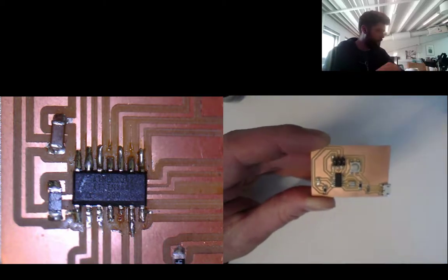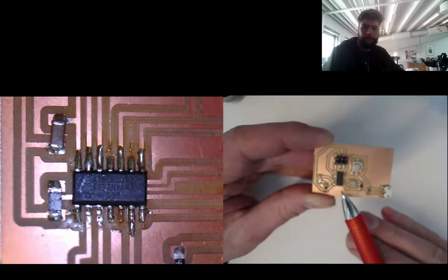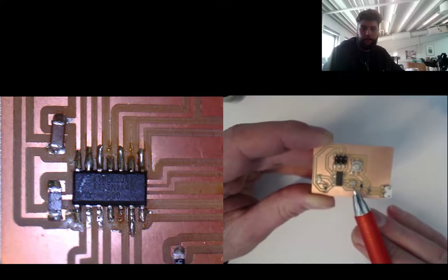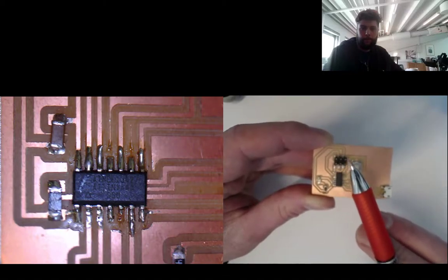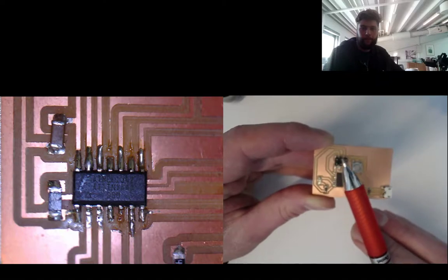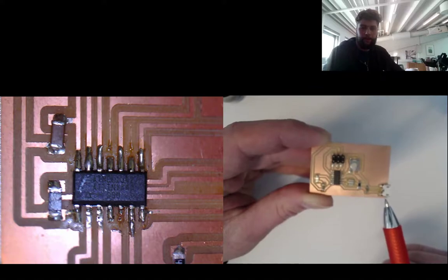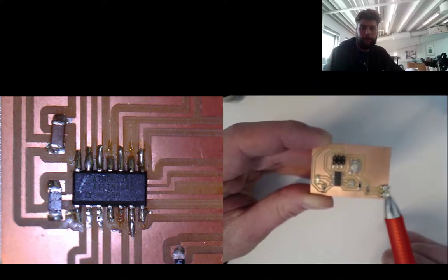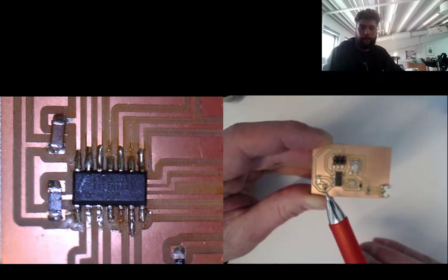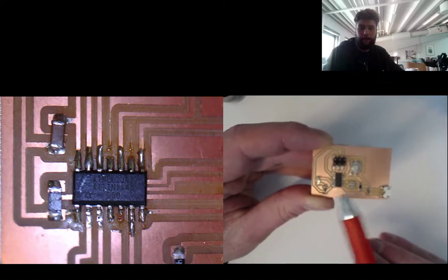It consists of the brains. It's the same brain as in the Arduino, just a much smaller form factor. It has a clock. This is a crystal, or a resonator, as it's called. And then it has programmable pin headers, the same as on the ISP. This one specifically has a USB port, which can be used to power the board, but for nothing else. And then it has some capacitors, resistors, an LED, and a button.